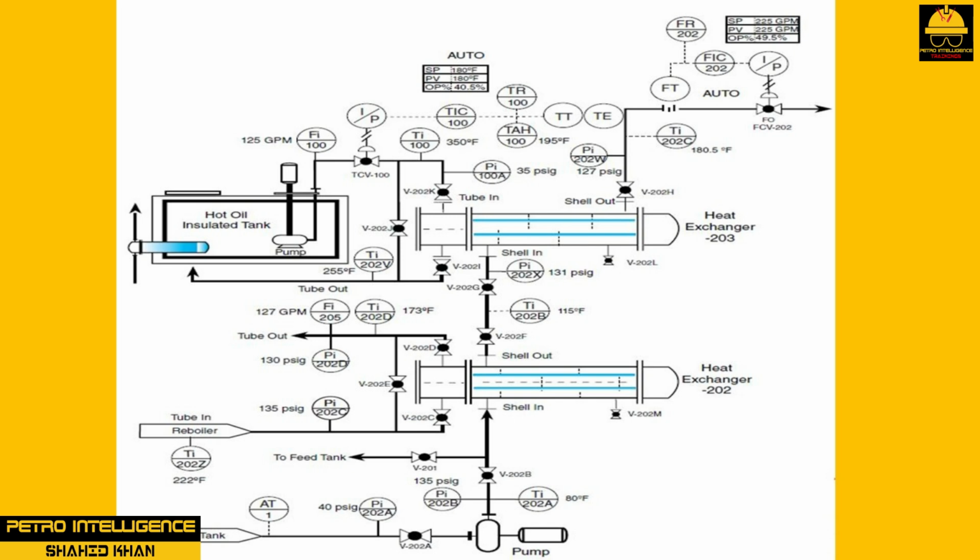18. Catch sample from EX202 at V202M sample port using all safety procedures and requirements. 19. Catch sample from EX203 at V202L sample port using all safety procedures and requirements. 20. Notify all involved of any operational changes to the heat transfer system.